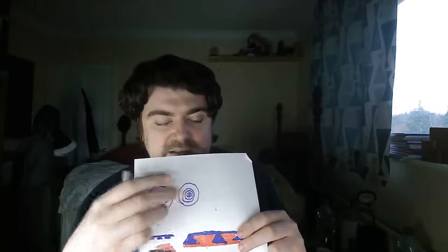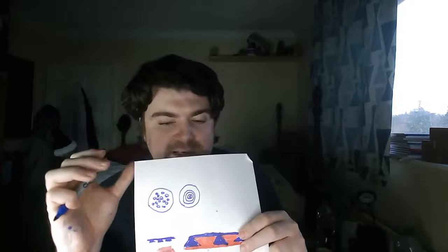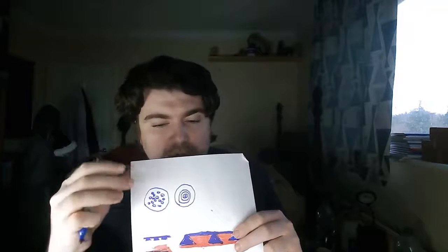Another shape would be what I call nested shape. So instead of having a gap in the middle, you just have rings, concentric rings, very, very thin concentric rings down the center. So it's like that. So all those are the gaps. The blue bits are the gaps, and they'd be the gaps down the length of the rocket. So you're looking into the tail of the rocket, and there'd be tons of those concentric rings. So the amount of fuel being burned simultaneously would be really high, and you wouldn't have to make them that deep because they'd reach the same power as one of the longer rockets.